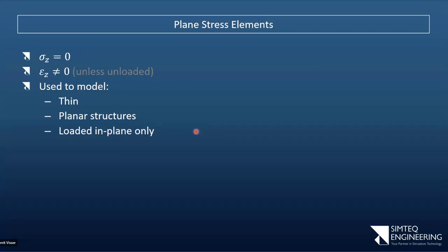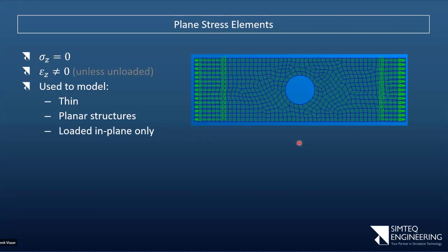The moment you have compressive load, you'll introduce buckling. Yes, when you apply a shear load, we can also get buckling, so that's also kind of a special case. So just be careful of this. This is the classical example of when we'd want to use this. We've got a thin plate with a hole in it. I want to calculate the stress concentration for those.